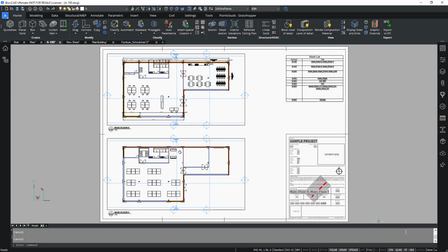Type plan. So you can import type plan templates shared from your design team, which you can apply to selected viewports on the sheets afterwards. These templates are helpful to ensure certain graphic standards are applied uniformly across different sets of drawings and across other projects, based on your desired entities of BIM properties and their values. It can also be useful to check if the 3D model elements and its metadata have been correctly created.